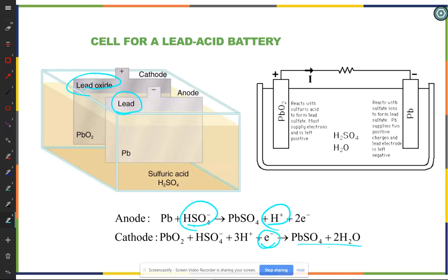But as soon as charge starts to flow, then your equilibrium in the battery is broken and the chemical reaction has to start up. So the battery should have its full terminal voltage, but as soon as you start to use it, the chemical reaction has to start up, and then your battery can only supply current at the rate that the chemical reaction can occur.